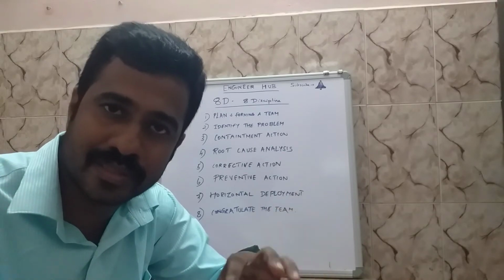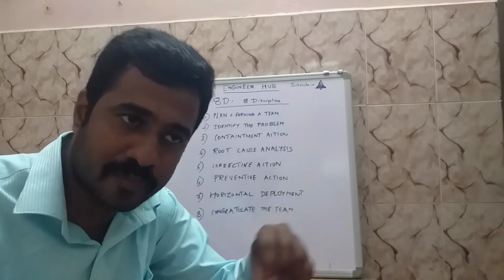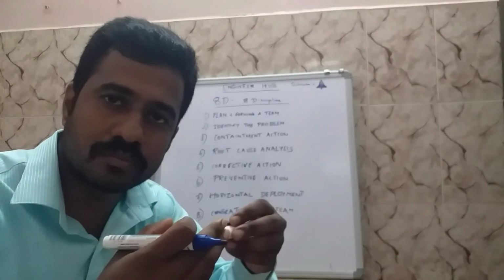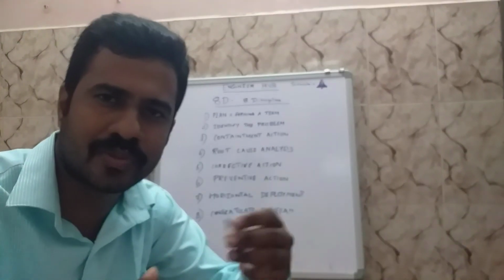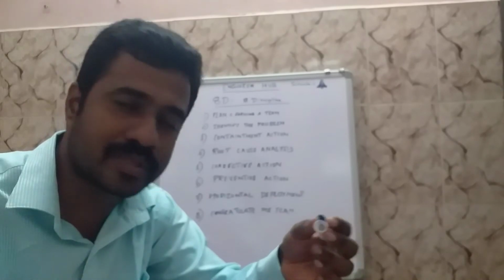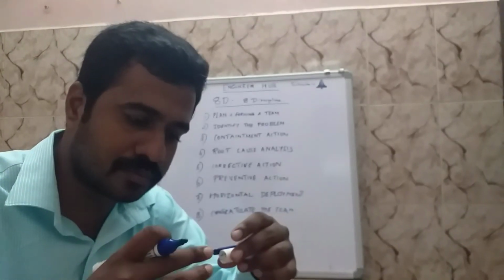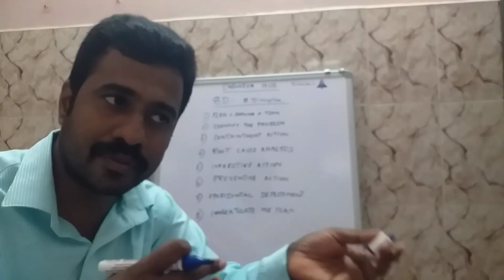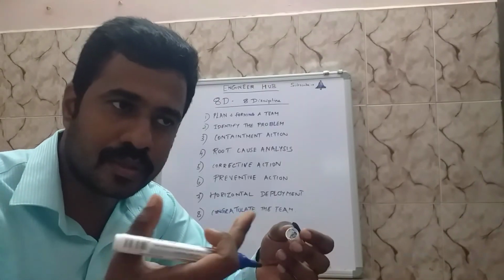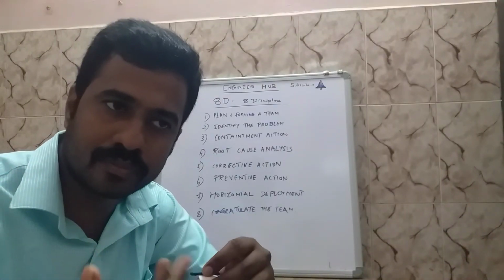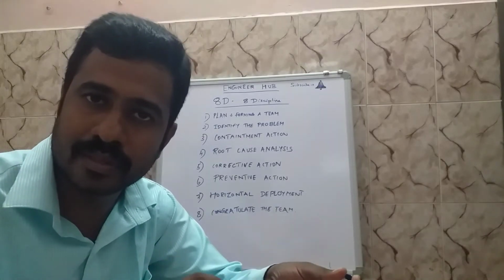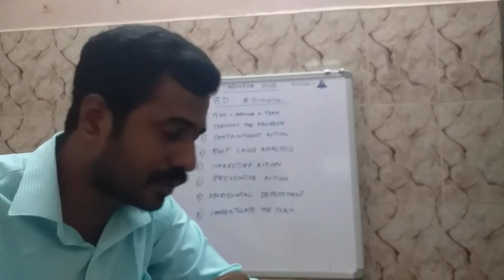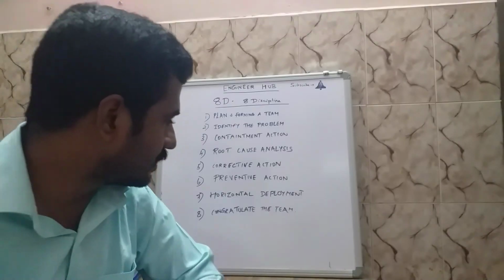And what are the checkpoints on the quality side? Before that, you must have checked the appearance issue and sent it back. So now we are using a gauge, making sure that even if it does get produced, it can get caught in the quality inspection, and the defect does not go to the end user. So that is the preventive action.